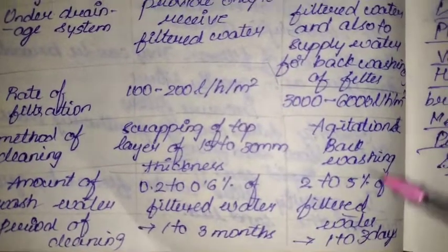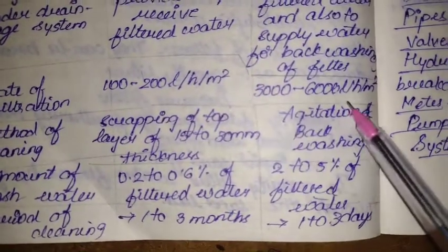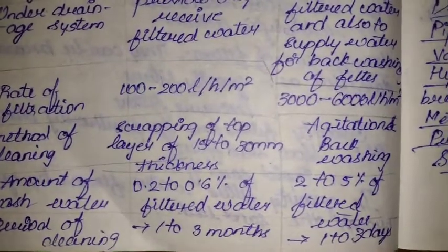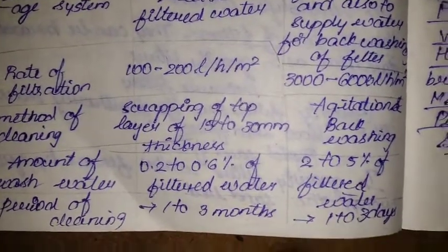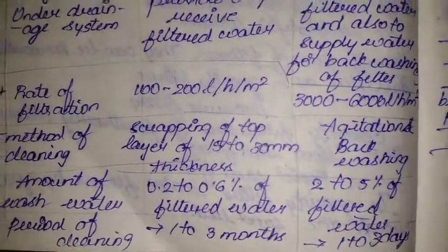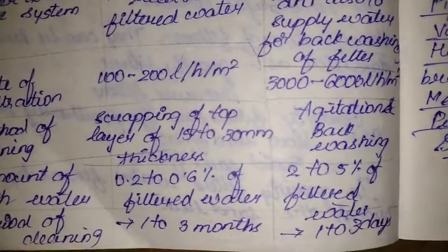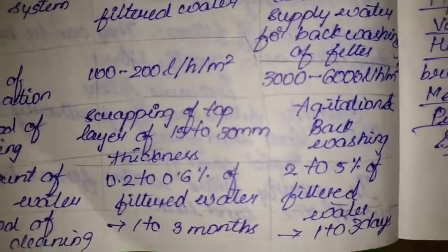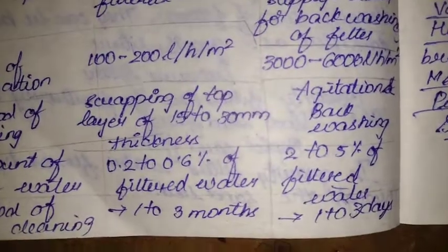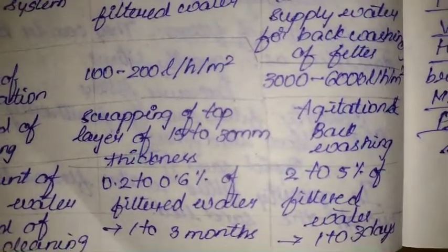See the variation, as even the water quantity that is being filtered is changing, the time taken to wash this will also be getting reduced. The more the water, the more sludge on top, the more skin on top. So we have to clean it very fast. Okay, for every 1 to 3 days we have to clean that.